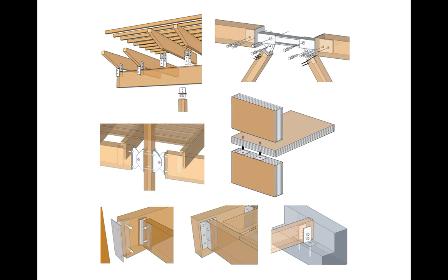In other cases, to make pin connections at the ends of timber elements that allow for some ductility, allow for some movement. Again, taking care not to put too much shear stress into the wood elements themselves, not to pull a pin through the grain, but to find ways to let steel do some of that work and to make the precise pin connections that we like in a ductile structure.